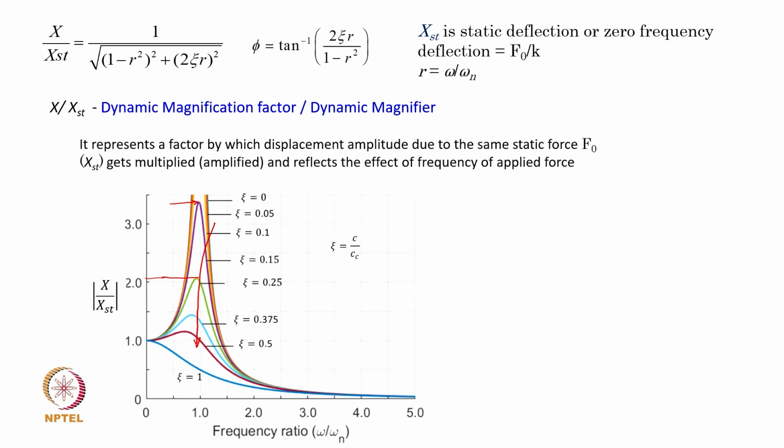For example, if I am operating at a frequency omega which is maybe 2.7 times the natural frequency of the system, or even 3 times, I will have to go from 0 to this frequency, and I will eventually encounter resonance. And so, if I have higher damping in the system,